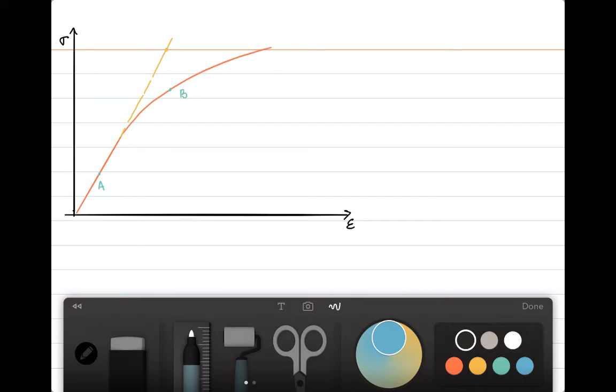But at some point, of course, there is some kind of plasticity, which is a contribution of both elastic strains and plastic strains, and follows the path which is moving more towards the right with the point B on it. Now, let us assume that we already know what the value of the stress is at the point A, and that is given as sigma A. And sigma A lies on the elastic region in this property.